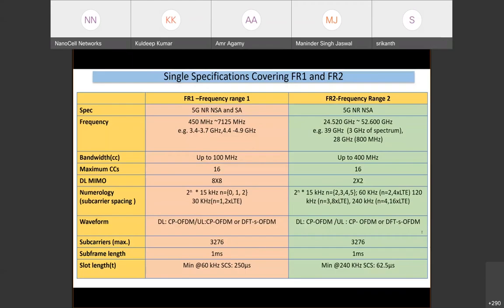That's correct, Amar, because typically with FR2 coverage, remember that more than distance, we usually talk path loss, etc. It does vary a lot on an environment basis. So typically people are using FR2, at least in the more traditional deployment, primarily for hotspot kind of areas, which these days serve about several 100 meters of cell radius. Whereas your typical FR1 deployment can cater to several kilometers in a classical deployment. However, remember FR2 with special antennas on both ends is being targeted for fixed wireless access.